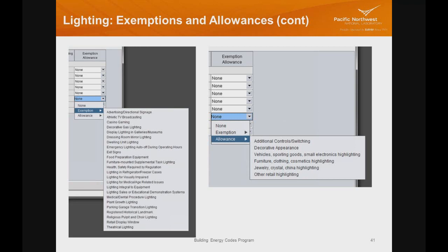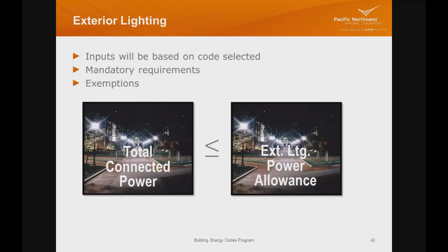If you pick an allowance, you generally will then be asked what the square footage of the area being lit is for that allowance. It's generally not the whole area type that you've got the fixture added to. It's usually a display case or sconce or something more focused in your space use type.